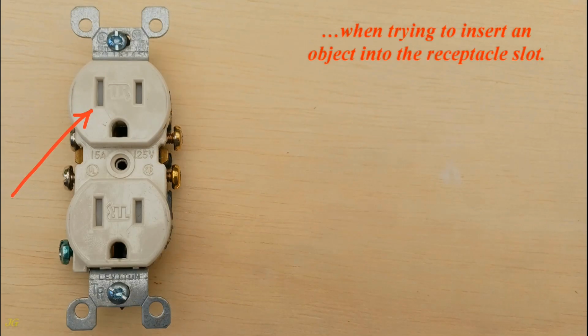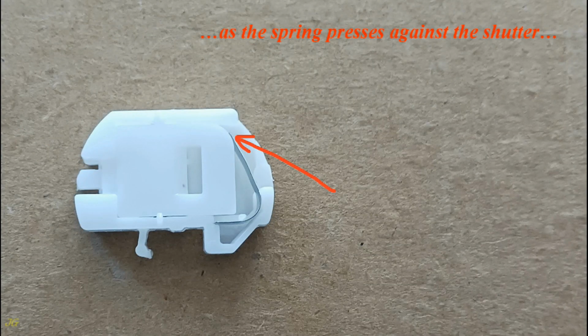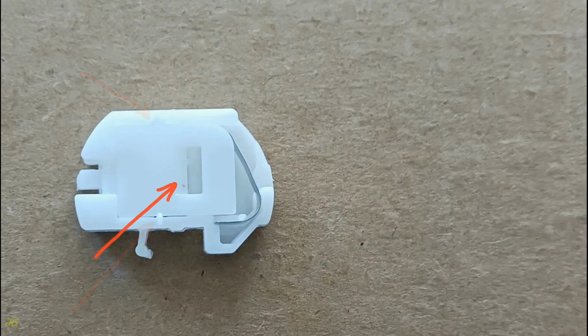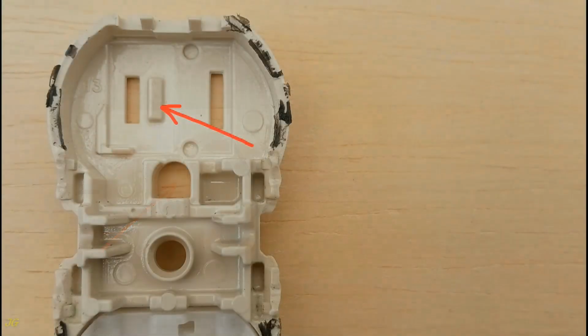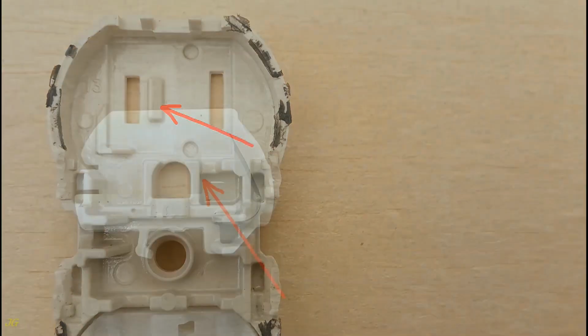When trying to insert an object into the receptacle slot, the shutter is stopped by the edge of the shutter base, as the spring presses against the shutter and the pins hold the shutter inside the shutter base. The conical side of the slot in the shutter slides over the conical post in the front base of the receptacle when the shutter is balanced and pressed evenly.